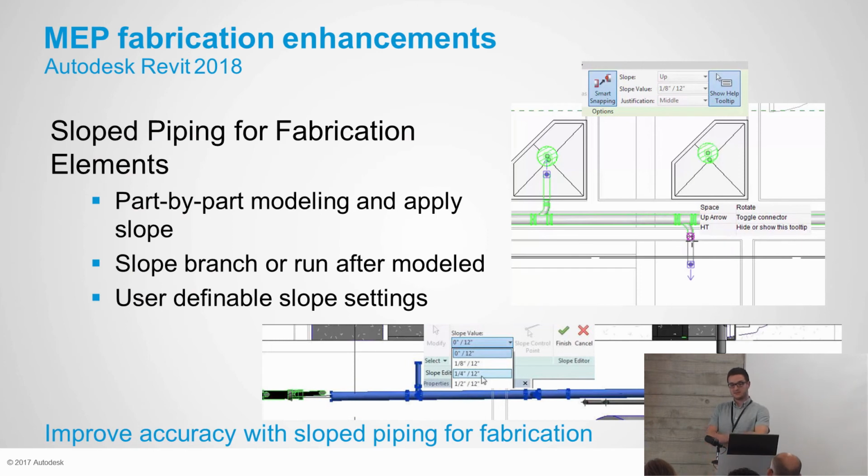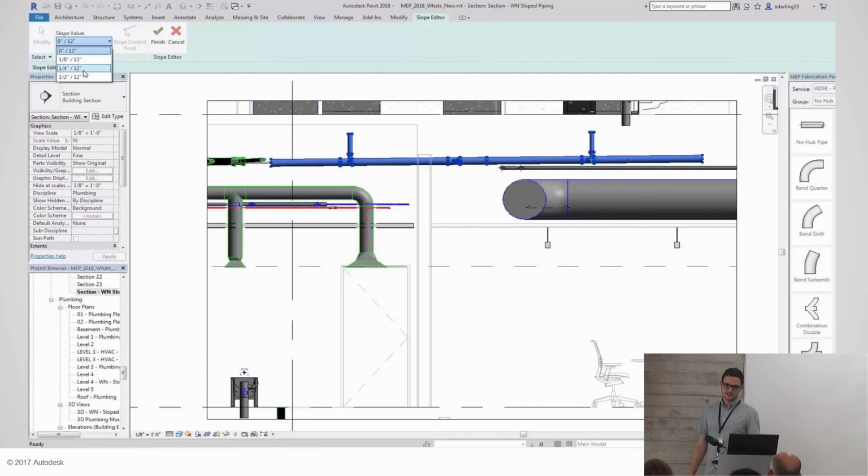Now the fab parts, this is something I disagree with. I don't know if there are any contractors using this, but once you put these parts in, they become dumb. Any information that you build into it, if we're building an asset model for your client or you're trying to run calculations, you swap that out for a fab part, it just becomes dumb. I know it is a real life component, off the shelf and manufactured, but I really don't see the point of losing all that intelligence. If you then hand that model over to the client, it's just a dumb model. It's like, well, what are we going to do with this? But obviously they see it as a big thing.